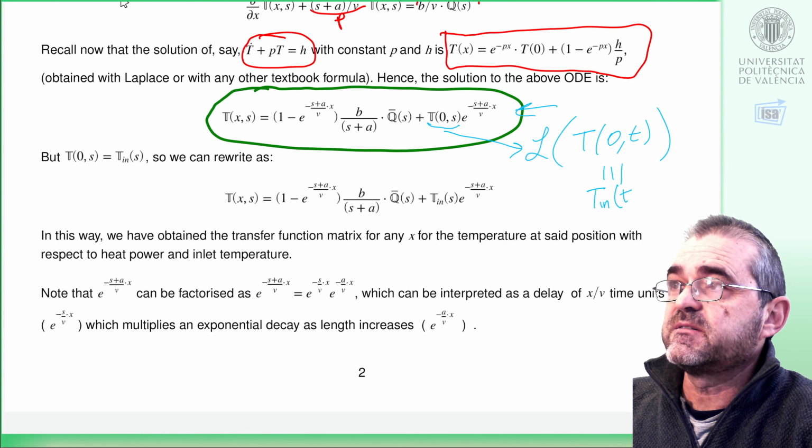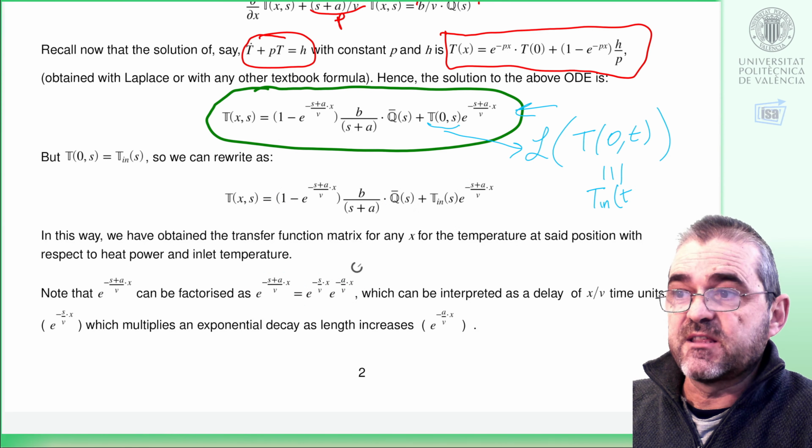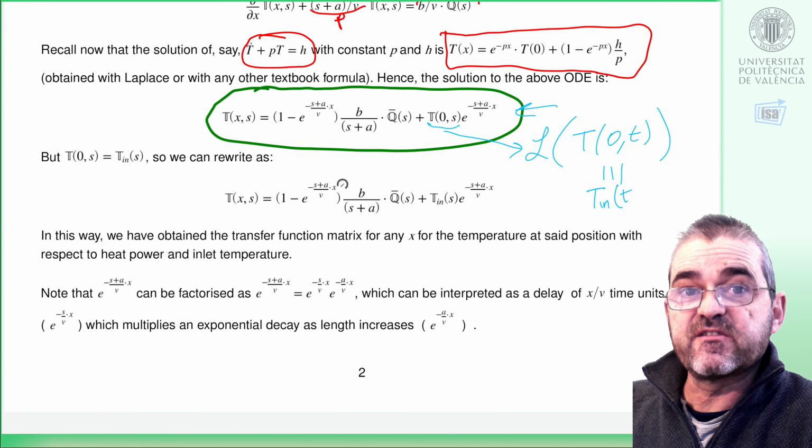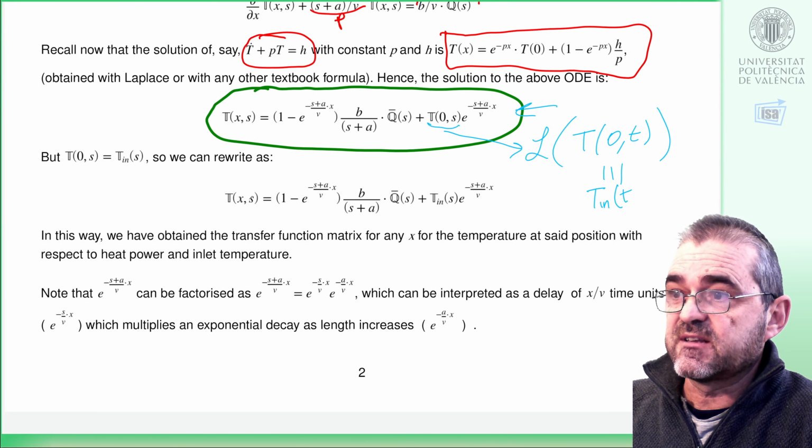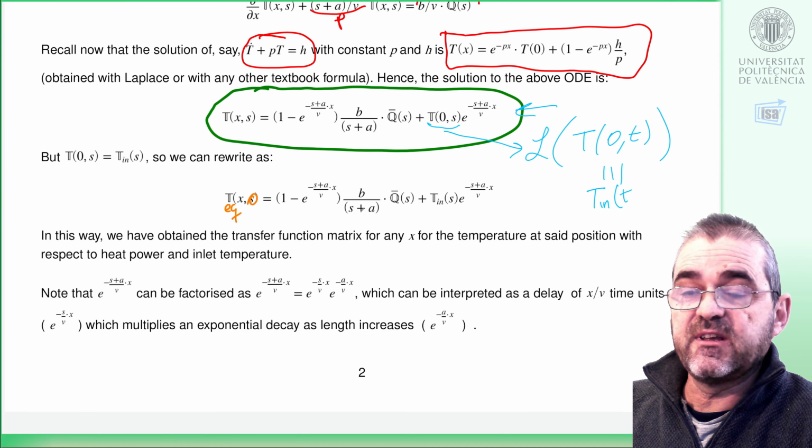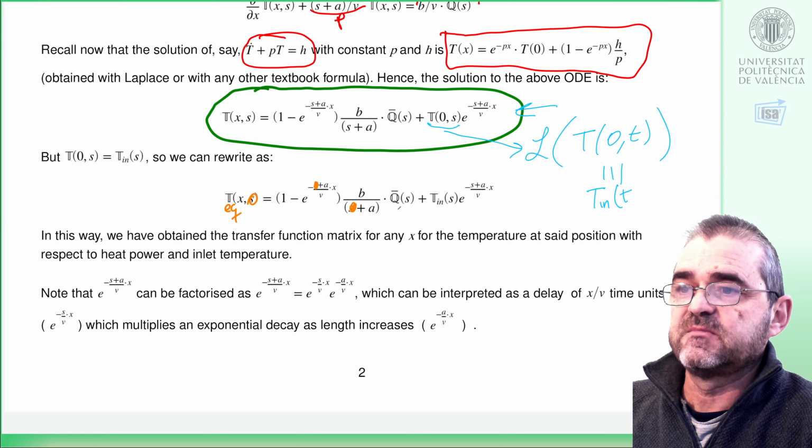It's important to see that if we want to get steady state, once we are in the transfer function, Laplace domain, we need to set s to 0. So we get the equilibrium temperature equal to the transfer function gain, setting s to 0, times the equilibrium input.